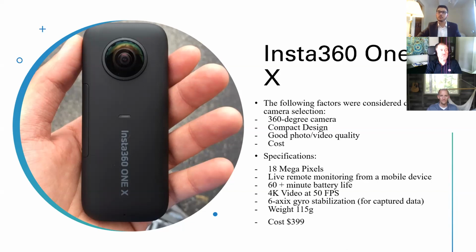That's why we wanted a robot that either already has a 360 camera, or, if not, we're going to modify it. From our research, we saw that almost no programmable drones and no programmable UGVs had 360 cameras. So this was something that we had to do ourselves. The factors that we considered for this selection were, obviously, a 360-degree camera. It should be compact, the smallest design possible, because we're putting it on the robot, good photo and video quality, and cost.